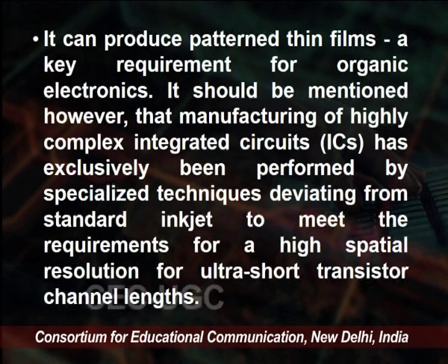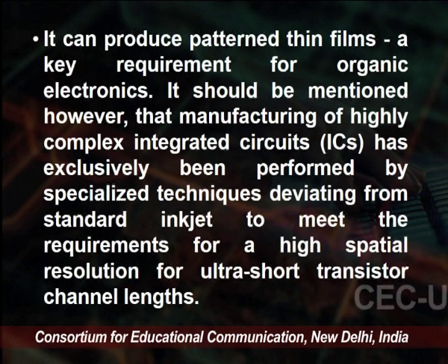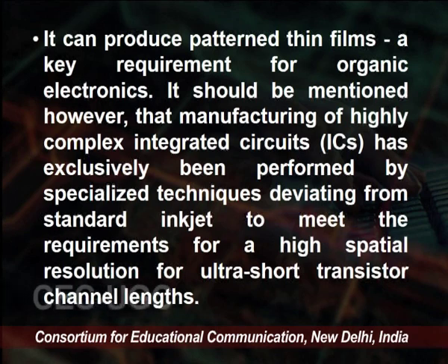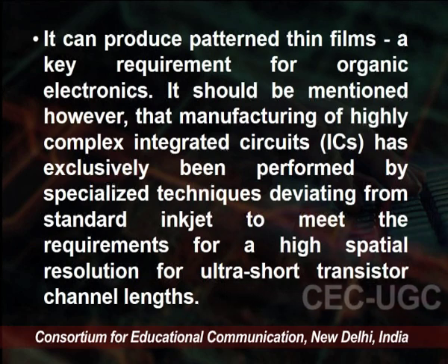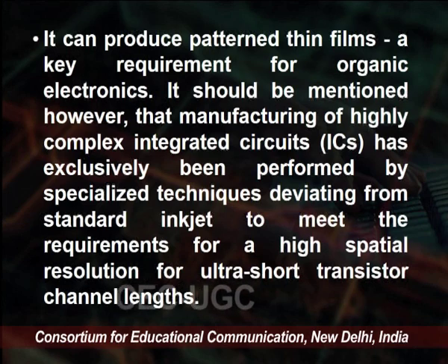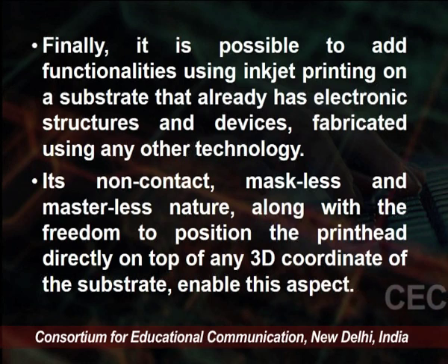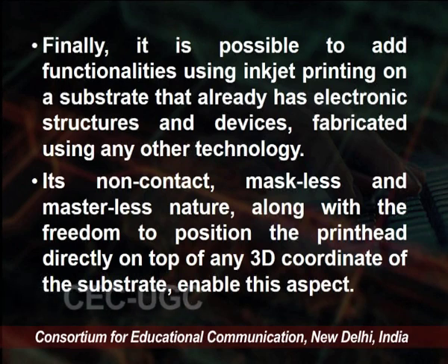It shall be mentioned, however, that the manufacturing of highly complex integrated circuits has exclusively been performed by specialized techniques deviating from standard inkjet, to meet the requirement of high spatial resolution for ultra short transistor channel length. Finally, it is possible to add functionality using inkjet printing on a substrate that already has electronic structures and devices fabricated using any other technology.